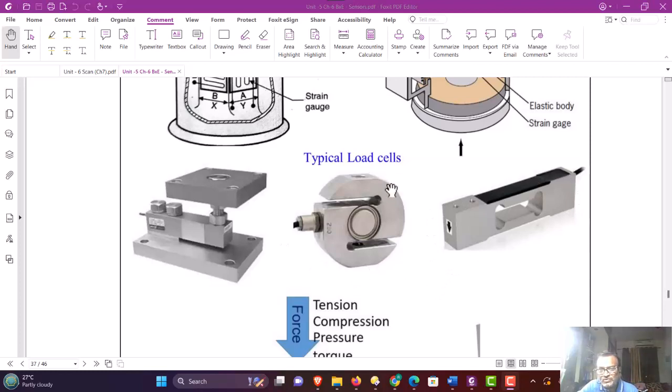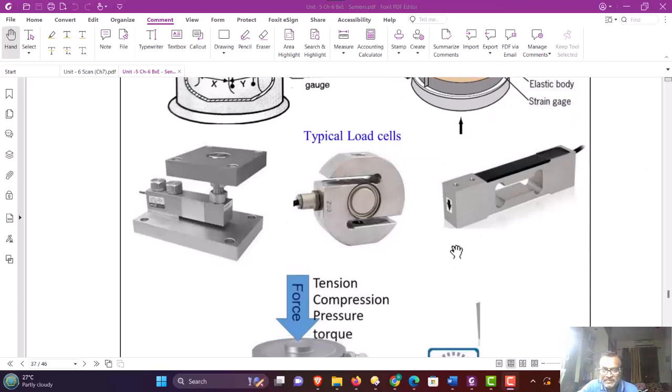Another structure is shown here. So whenever the pressure is applied here, there is a deformation of this slot. So in this slot, the strain gauges are pasted. One is from the bottom side of this top edge and another is shown here on this portion. So therefore, when strain is applied, there is a change in resistance of the strain gauge, and these strain gauge wires are connected and available for external connection via wires.